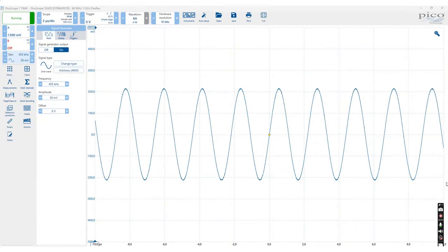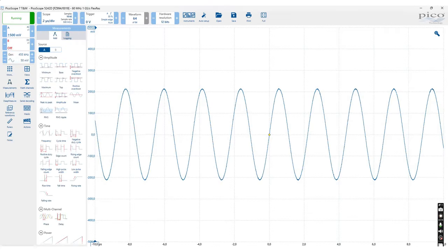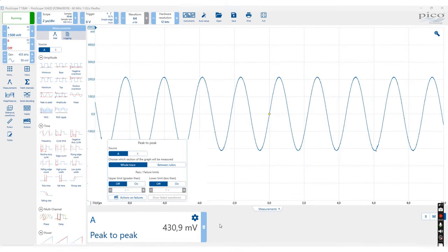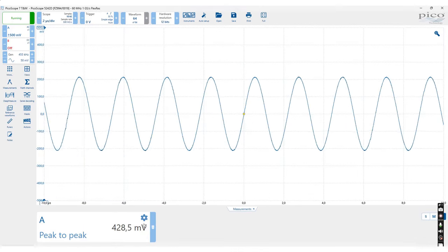Before we move on to the frequency domain, let's take a look at the basic operation in this current setup. With a 455 kHz input signal at 50 mV amplitude, the output is already above 200 mV. So in this configuration the amplifier provides roughly a 4 times gain, with plenty of headroom left.